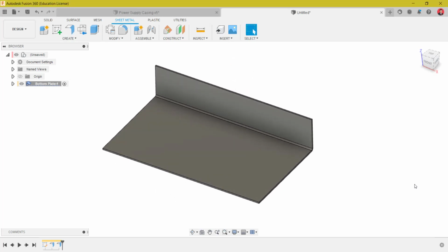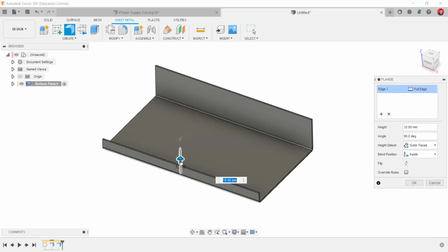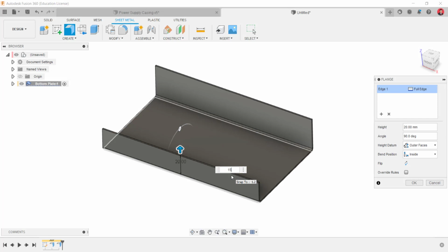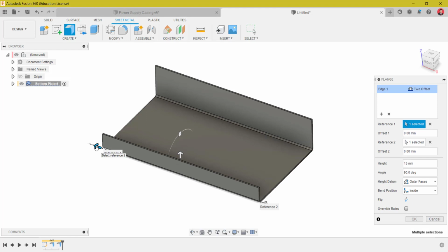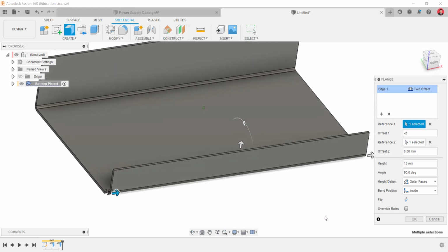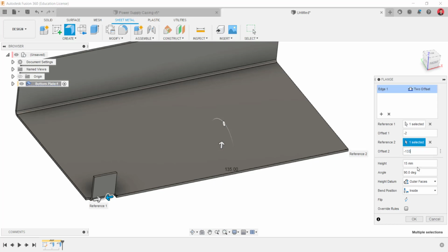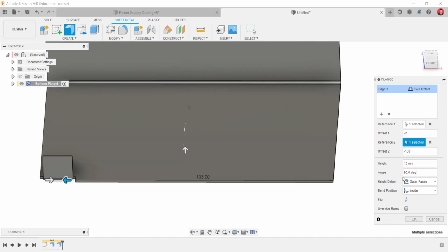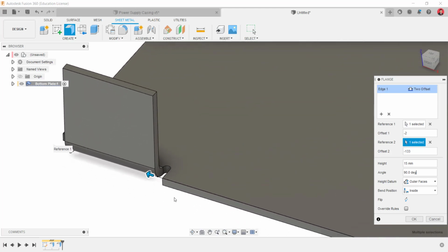and then make the flange again in the front position with the 15, and right now I will choose the edge option as the offset edge, because I don't want to make a flange on all of the edges but only on part of the edges, so I can just drag the option, and also we can fill in how much the offset is, and then the angle you can choose, whether the bend radius is.